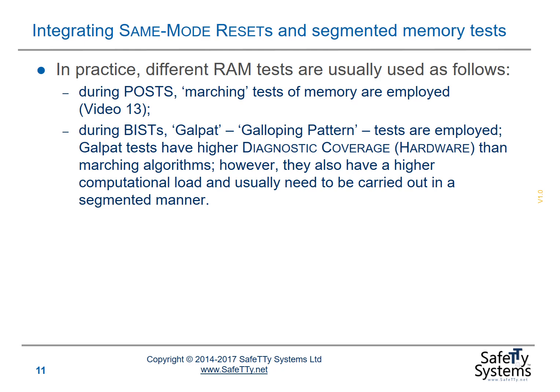GALPAT tests have a higher diagnostic coverage for hardware than marching algorithms. However, they also have a higher computational load, and they usually need to be carried out in a segmented manner, as we discussed in a previous slide.